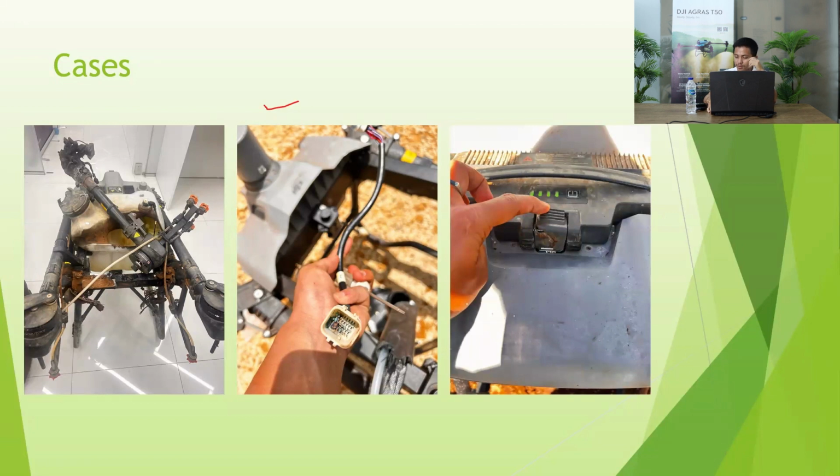Okay, maybe sometimes you install the battery, you didn't hear the click. Why? Because maybe the clip is damaged or broken. Okay, be careful, especially if you don't clean well. It can also happen by chemical erosion and fertilizer. Then it can easily crack also. So you have to wash all the time and dry clothes. Everything, you have to clean your batteries and drone and remote controller.